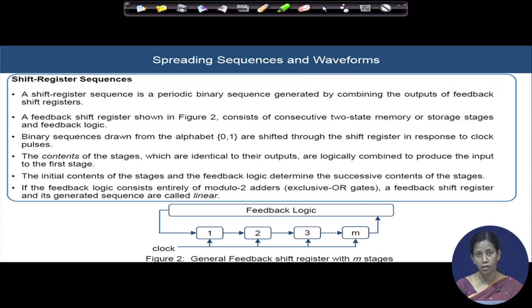It has a nice autocorrelation function, but the problem is that in any practical system design, for synchronization purposes, we understood that for direct sequence spread spectrum as well as for frequency hopping spread spectrum, timing, phase and frequency synchronization will be very critical, because you have hopping involved in the frequency hopping spread spectrum, and in direct sequence cases you have to be well aligned in time with the incoming signal, otherwise it will be very hard to despread your signal and demodulate your signal.